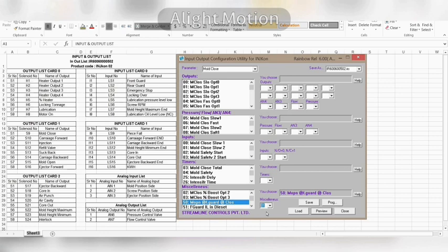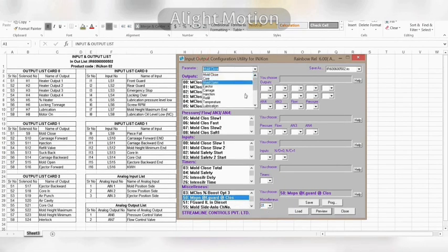One more example we will see. As soon as you press emergency stop on your machine, if your mold is closed, then our mold should open. Then we have to enable this interlock. So in the parameter, in the mold close, we will go into the miscellaneous. You can see parameter number 124 in it: Mold open if close at emergency.